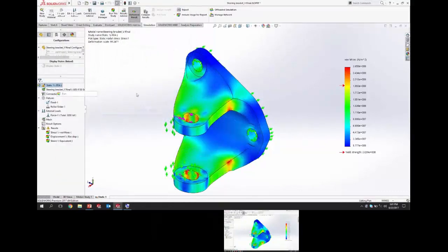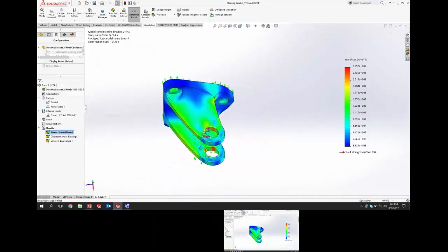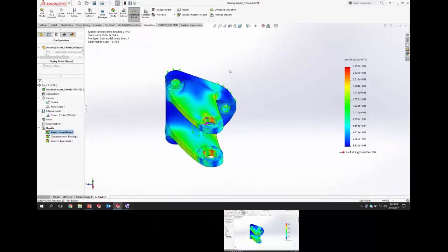Okay, and just like with thermal analysis, the great thing is you can make an adjustment, rerun the study, and test again very quickly. And now we're roughly a little over half, two-thirds of yield on the material. Well, I like the basic idea, but maybe I really want to understand what's happening with contact stresses around this part of the component. So let's see where we can go with this a little further.